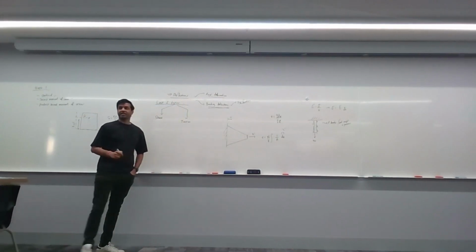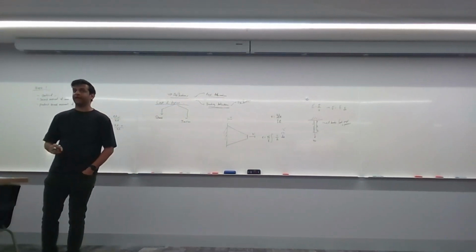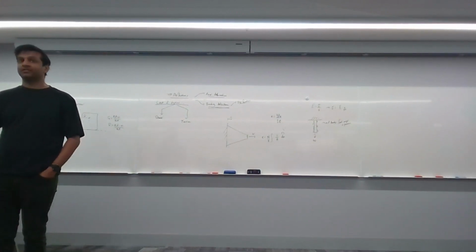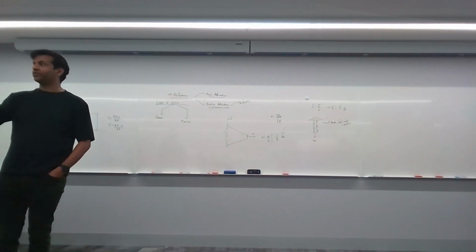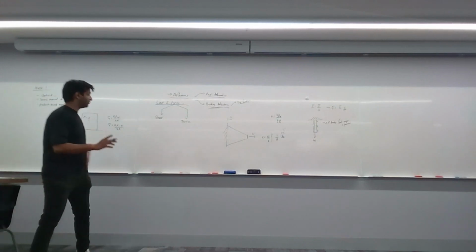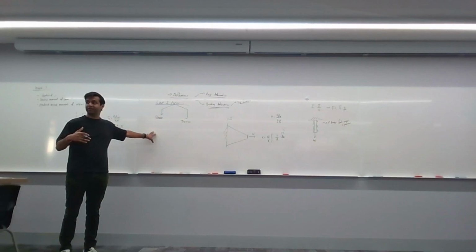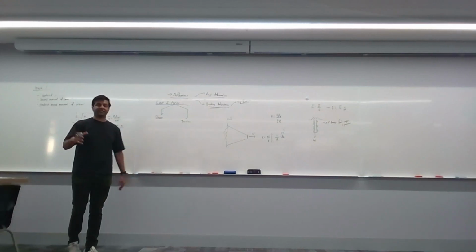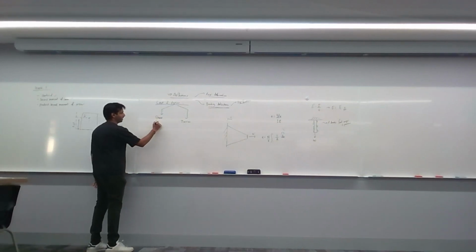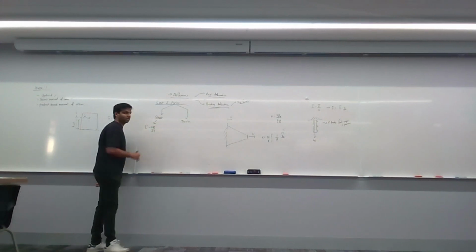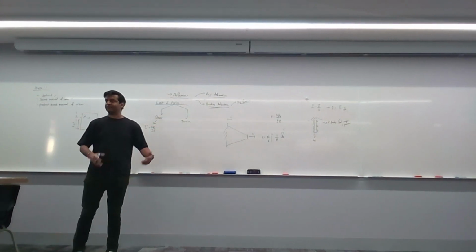The last two topics are shear and torsion. Again, I'm not going to go through in specifics what each topic is about, but a couple of important things to point out. Firstly, for shear, there is a common misconception about this topic. We know that there's the popular formula here, tau is equal to VQ over IT, or VQ over IB, however you spin it, it's the same formula, right?